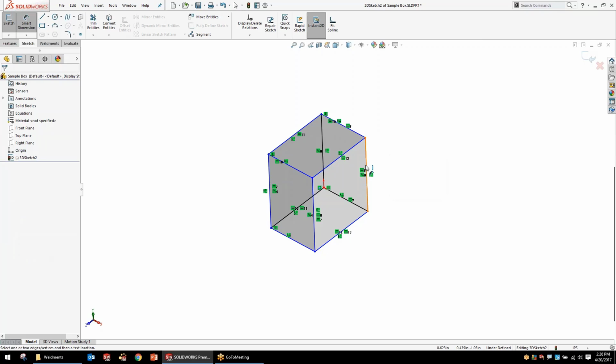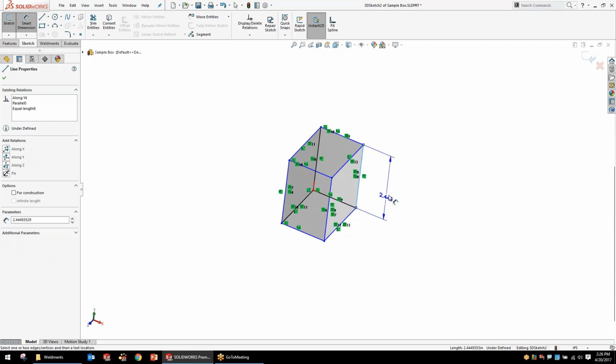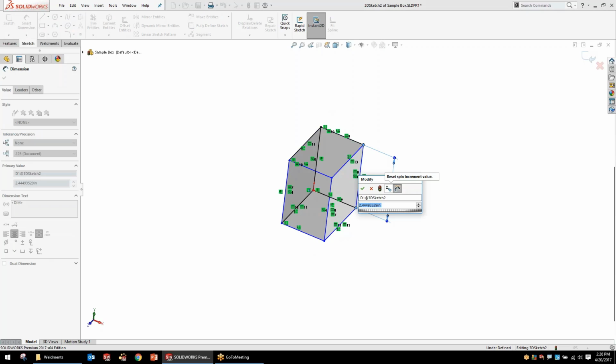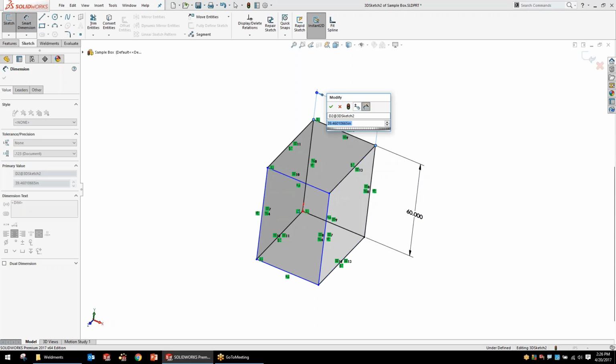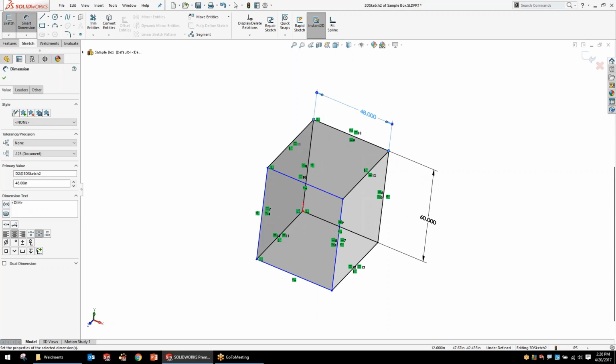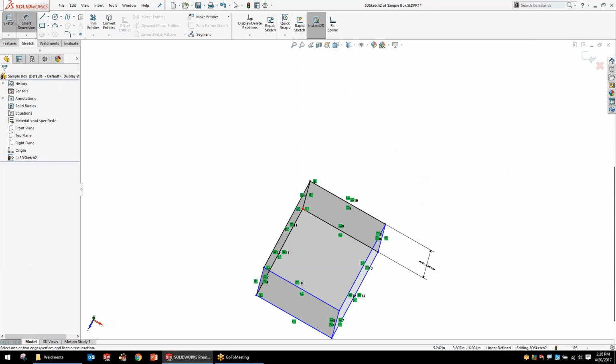Now I'm going to show you dimensioning. Notice that the dimension's off to the side in the one plane that it's working with. Let's say that we want our box to be 5 feet tall and 4 feet wide, but I want that dimension to sit flat with the top surface. The big thing is it's going to try to grab the plane that is more normal to the dimension.